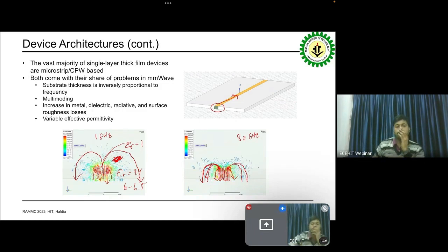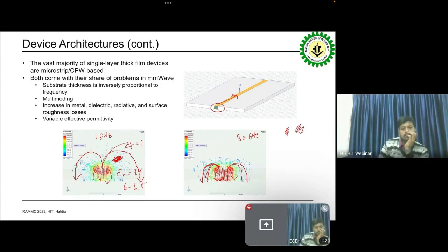And so if I'm designing for a 10 mil thickness substrate, my line width at 5 gigahertz, for example, might be something along the lines of 9.8 mils. Let me get my hand on here so I can actually write. So 9.8 mils at 1 gig. Up here at 80 gigahertz, and this is kind of counterintuitive, the line width will actually increase, not decrease. So you would expect a need for a higher impedance, but you're actually reducing it in order to accommodate that. So at 80 gigahertz, your line width might be something around 13 to 14 mils. And that's a big jump.